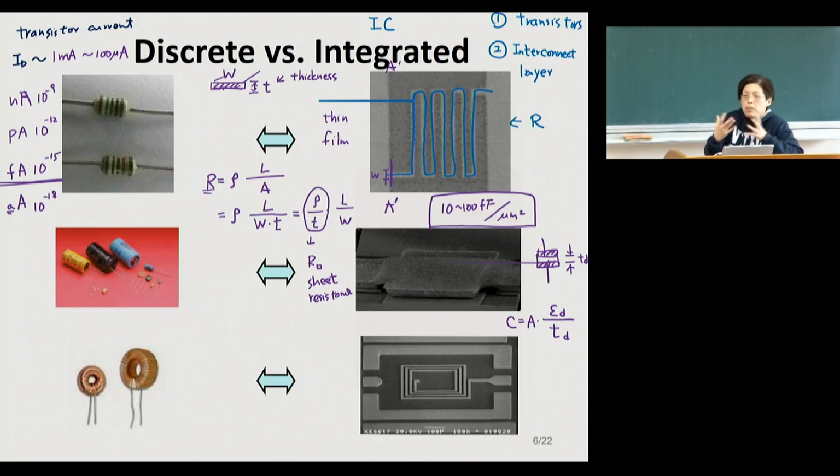Therefore, if you want to make large capacitance, you need to resort to external components. That is why in some circuits you will still see a big tank of capacitance, because you need that large capacitance for power reserve, or you want to do rectifying circuits at a lower frequency, and then you need large capacitance that is not cost effective to make in integrated circuits.